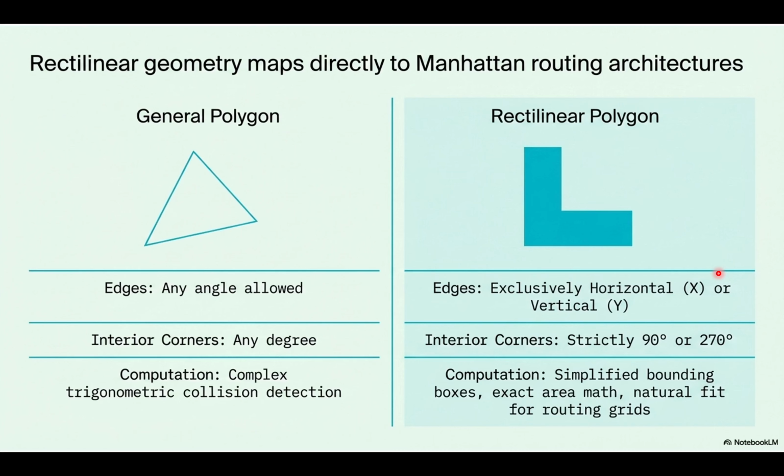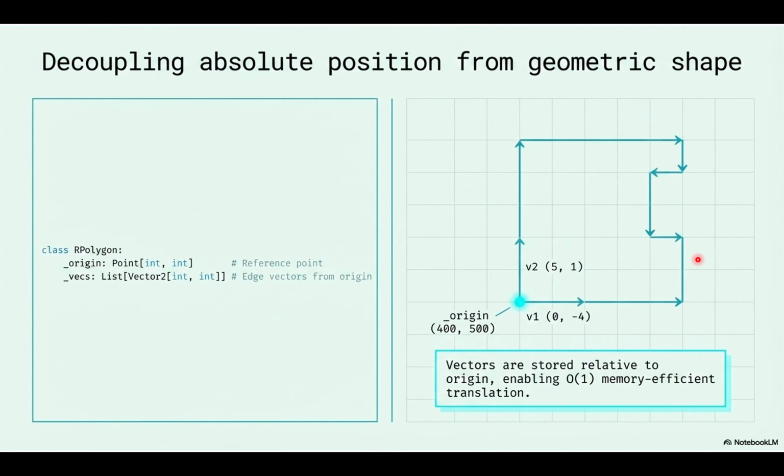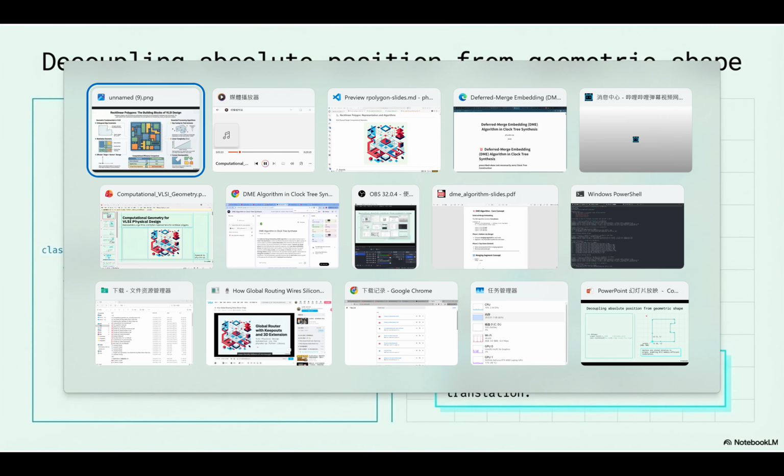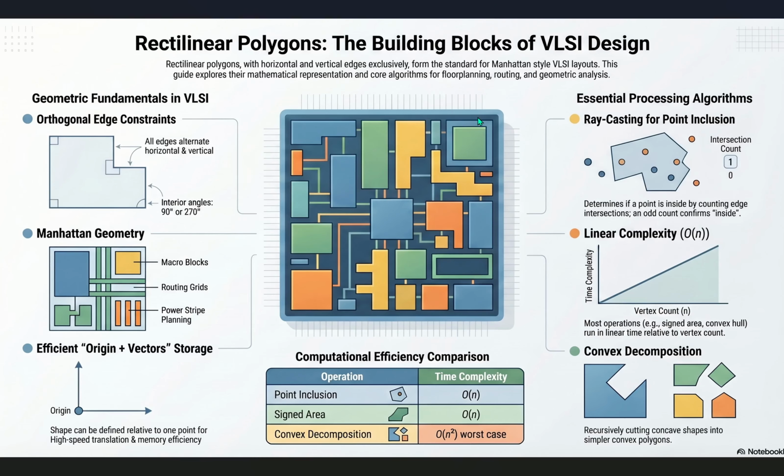It definitely seems that way until you look at the actual physical manufacturing process of VLSI, which is very large-scale integration. Okay, lay it on me. So a modern microchip isn't just a flat piece of paper. It is built in vertical layers. You have these distinct metal routing layers stacked on top of the silicon. Like floors in a skyscraper. Exactly. And to prevent crosstalk, which is signal interference, and to prevent manufacturing errors, these layers are heavily directional.